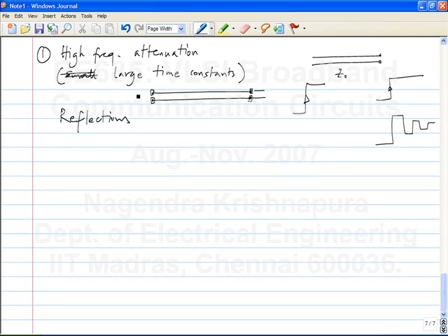And these reflections do occur because you simply can't make a uniform medium. For instance, with the Ethernet cable, it's no use having just a cable. Firstly, it's not uniform at all. Even if the cable were uniform, you have to connect it somewhere. The moment you make a connector, that becomes an impedance discontinuity. So there are various such things which impair the signal.